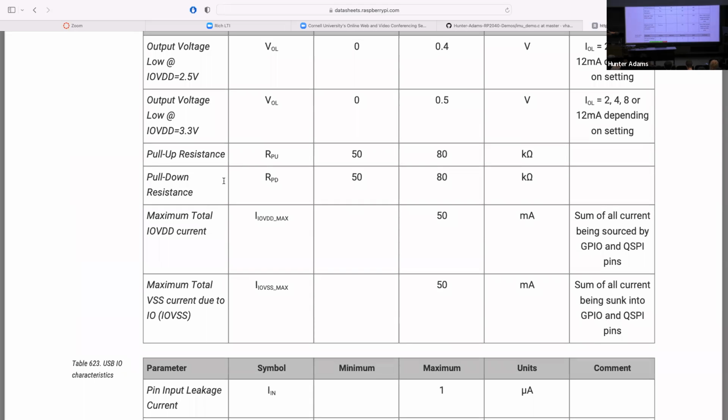So if you scope your I2C channel and you're using the pull-up resistors, what you might find is that the edges are a little bit soft, right? They aren't changing as quickly as you might want for them to be able to change. The reason that you would be seeing that is the internal pull-up resistors are too high than would be recommended for an I2C channel.